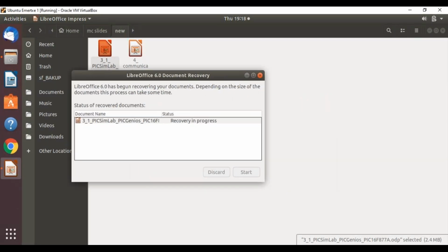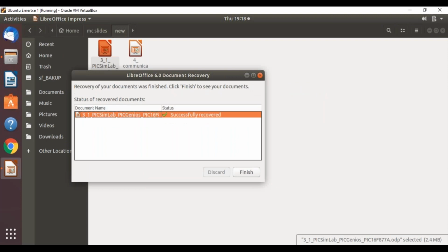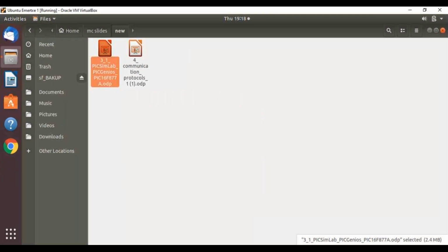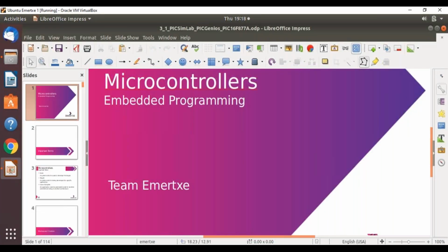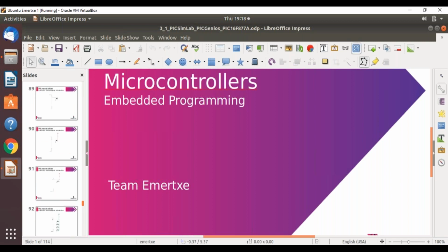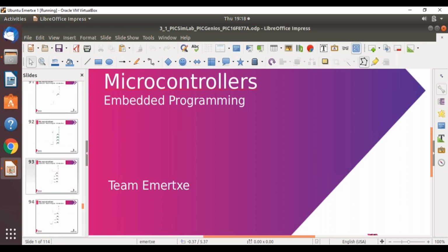In the matrix keypad, we were using certain pins. For the rows we were using port D, and for the columns we were using port B. While having the matrix keypad in use, we couldn't use the CLCD in 8-bit mode, so we used it in 4-bit mode.